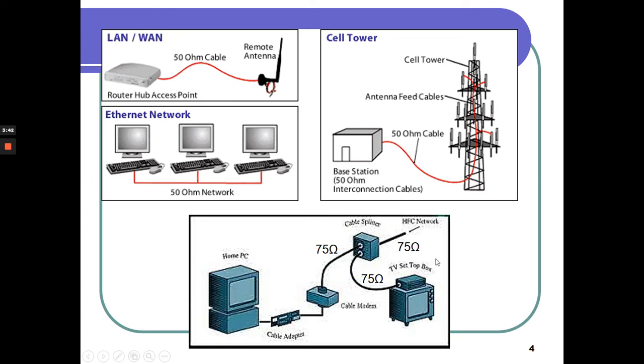However, for the TV network, cable TV and everything, usually the industrial grade is 75 ohm. So this is important, because based on this, the cable is designed. So basically we have 2 types. There are actually a few others, but industrially we have 2 different grades, which are 50 and 75 ohm characteristic impedance